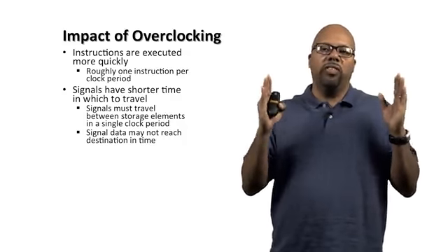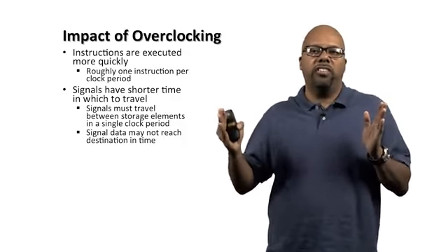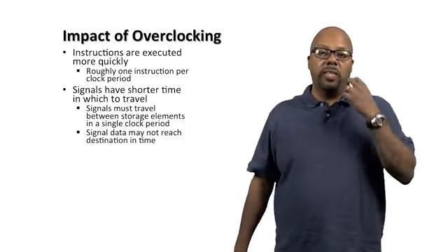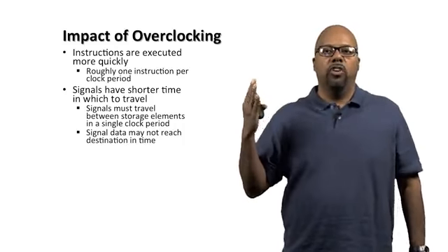If you reduce the clock period too much, these signals won't have time to get to their destinations before the next clock period, and then something will go wrong and the operating system will just crash on you. So that's sort of the downside, the main risk that you're taking by overclocking.